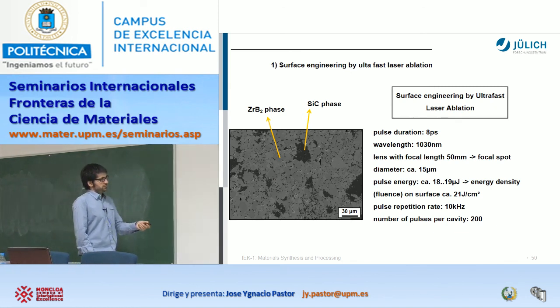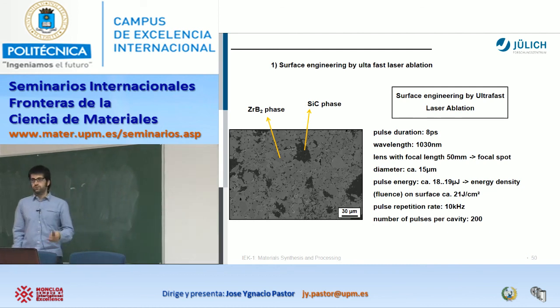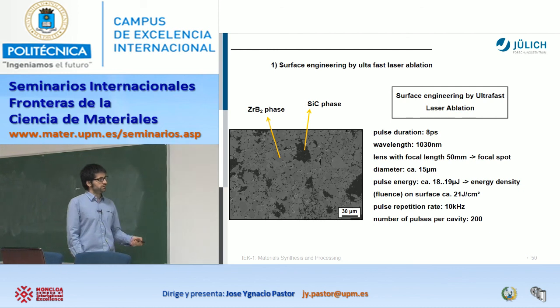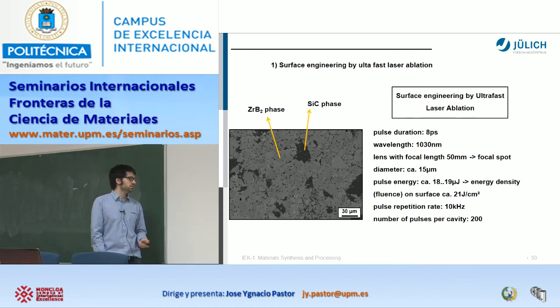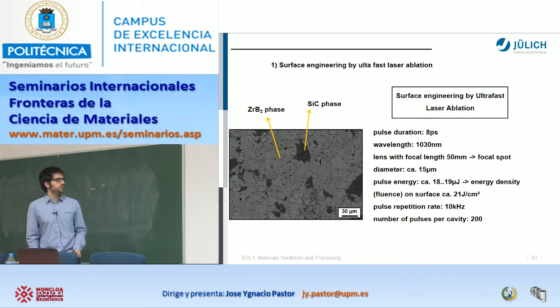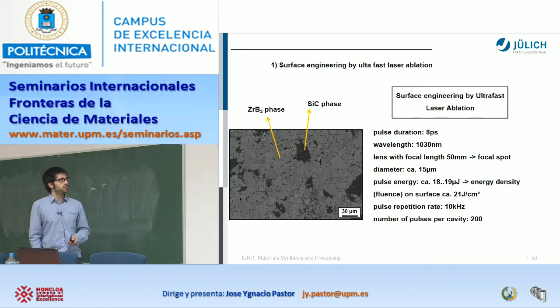And to do that, of course, I divide it into different steps. The first thing, I think this picture I showed you a few times. First, develop our zirconium diboride with the silicon carbide particles, okay? We densify at 2000 degrees, I think, in the SPS for sure, and then we obtain a dense material where there are a few pores, but the density was 99.5, something like that. Then we obtain our dense materials.